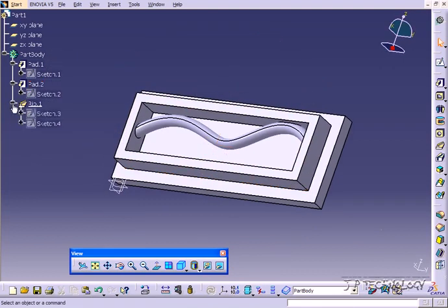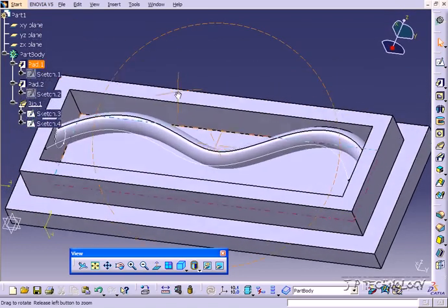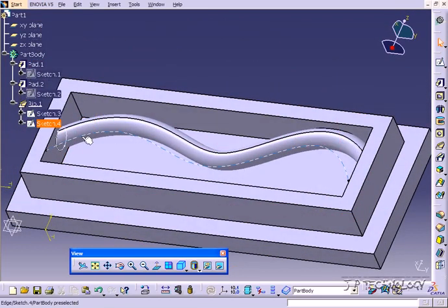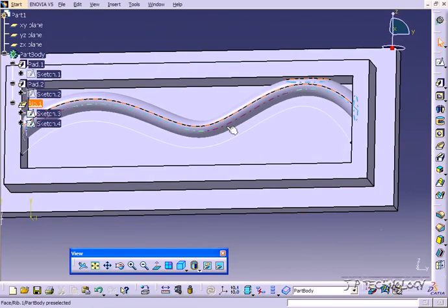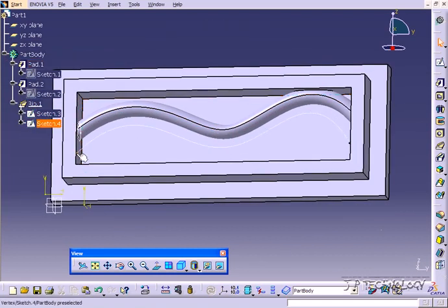Now open up the rib and let's show the sketches that we've been using. And you can notice that this line here is not actually touching the rib that we've cut out. So the sketch that you've made is going to automatically shift up or down to wherever the profile that you're going to use is. So as you can see, this has been shifted up to meet this profile and then follows that curve.